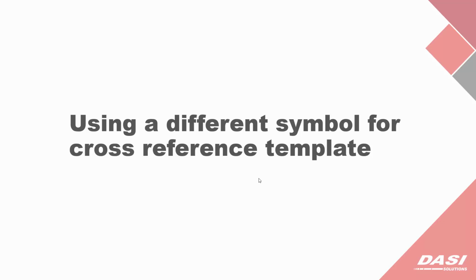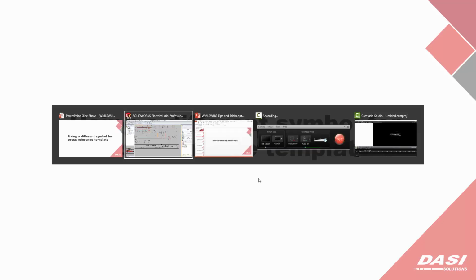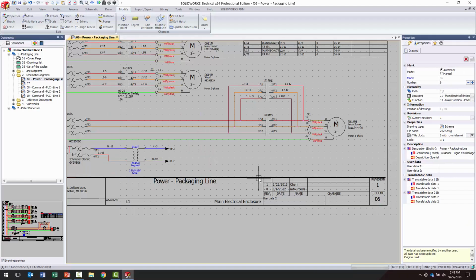That can become a little bit of a problem, because of course now when somebody is building a panel, if you're intermixing those symbols based off of what you're utilizing, it can become an issue for the cross-reference when people are looking at it saying, hey, I'm used to the old style where it was just the wire number or the location, and then it was the location with an underline for a normally closed contact, or normally open was just the location, and then it was a star for anything that was spare.